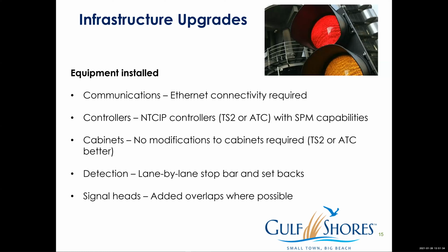The cabinets, really no modifications to the cabinets. Any cabinet out there would work as long as we can get the detection that we need back into the controller. Most TS1 controller cabinets that use shelf mount detectors or some sort of in-pavement detection just don't have the capabilities to do what we need. So we're looking at using TS1 cabinets with above ground detection that has an SDLC interface to the controller.